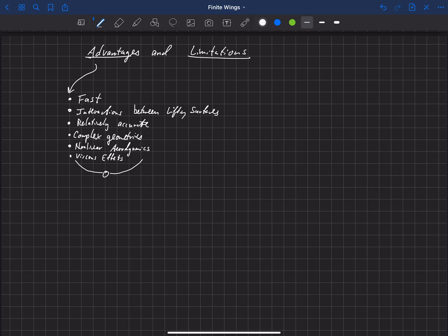Okay, however, it has some fairly significant limitations, so let's talk about that over here. First of all, this is inherently a potential flow method. Already, the fact that it's potential flow offers some limitations compared to CFD or experiment, where we're going to be neglecting things. We just are, by the nature of the equations that we've developed. We've thrown away the effects of viscosity in order to simplify the solutions down to this potential flow method. So anyway, that's just baked in.